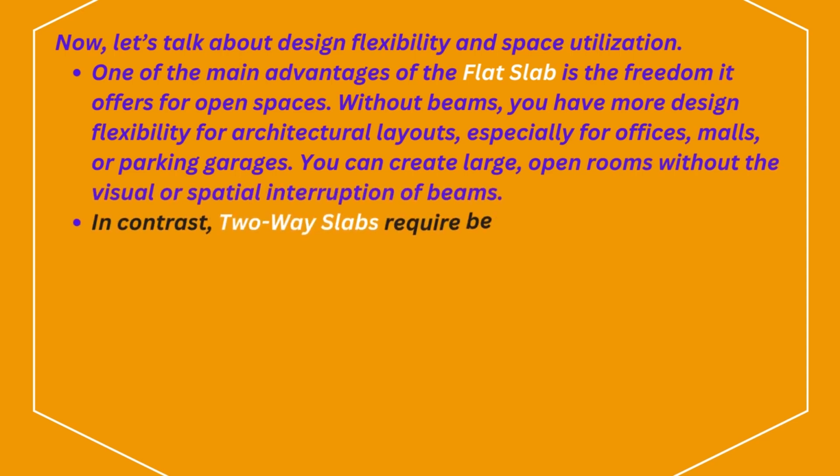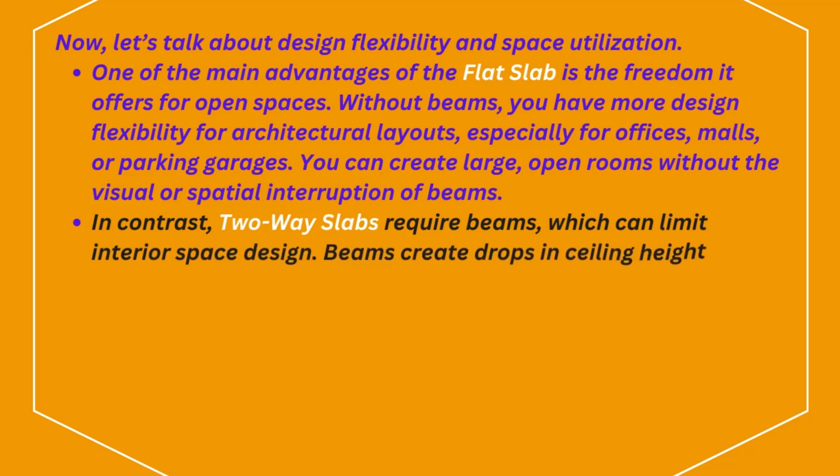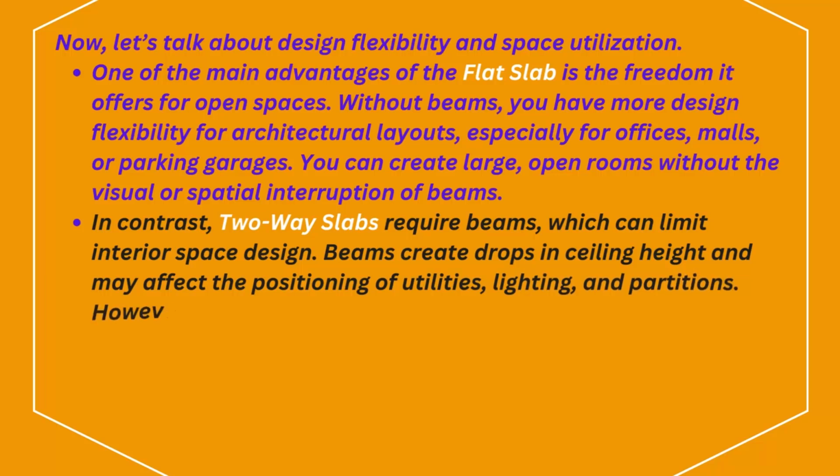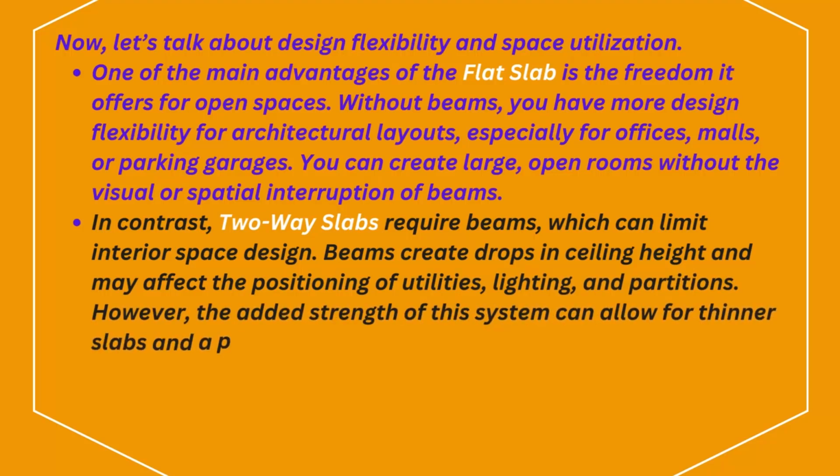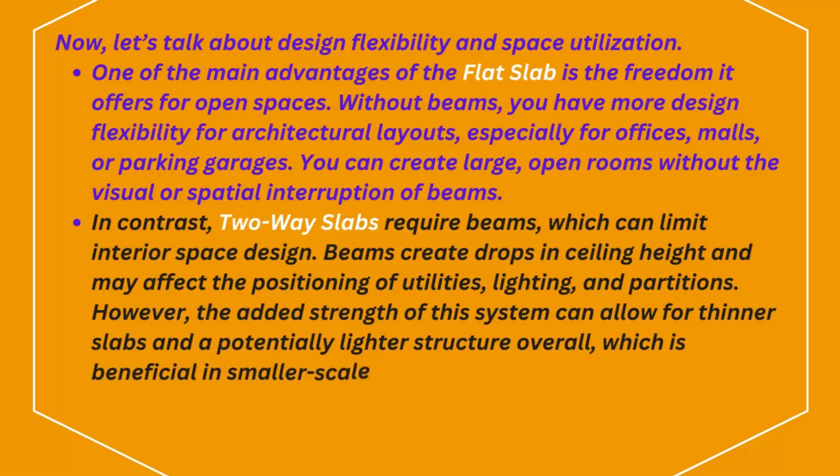In contrast, two-way slabs require beams, which can limit interior space design. Beams create drops in ceiling height and may affect the positioning of utilities, lighting, and partitions. However, the added strength of this system can allow for thinner slabs and a potentially lighter structure overall, which is beneficial in smaller-scale projects or residential buildings.